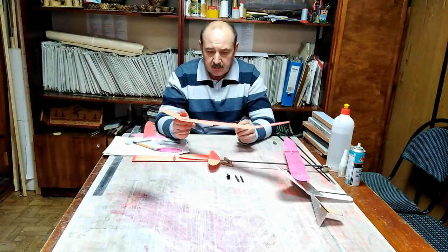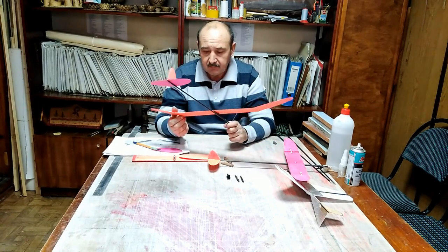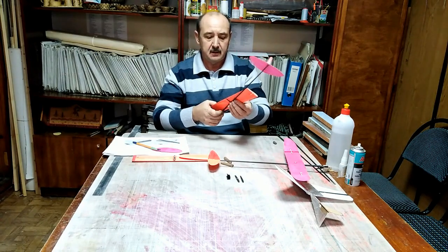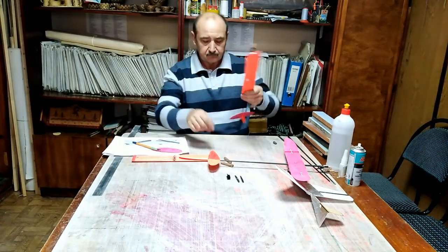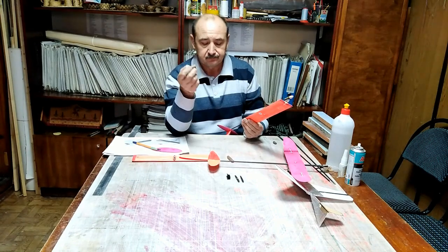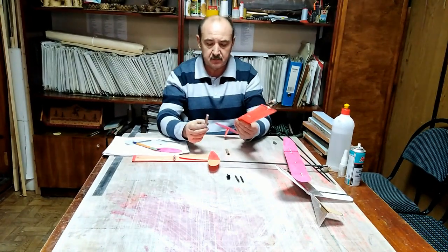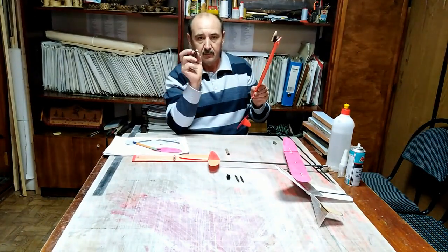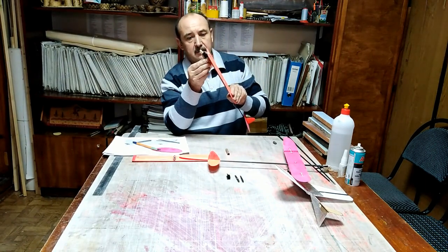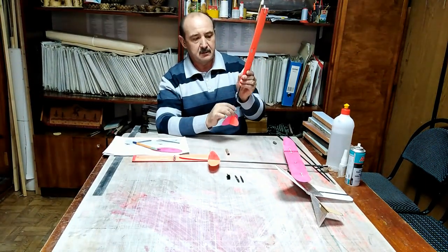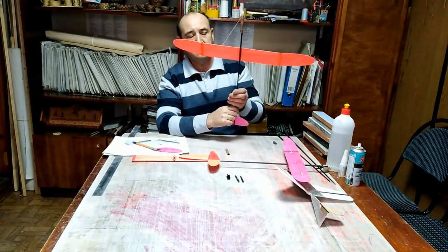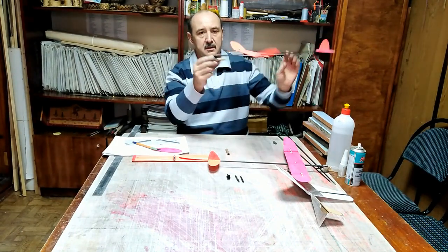This is a glider. It rises high up into the air with the use of such an engine. In the S4 class, we use engines with a delay from 2 to 3 seconds. The jet thrust of an engine allows the model to rise high up into the air, and when the delay acts, the delay burns the thread here, and the wings open like this. And then we observe aerodynamic planing.